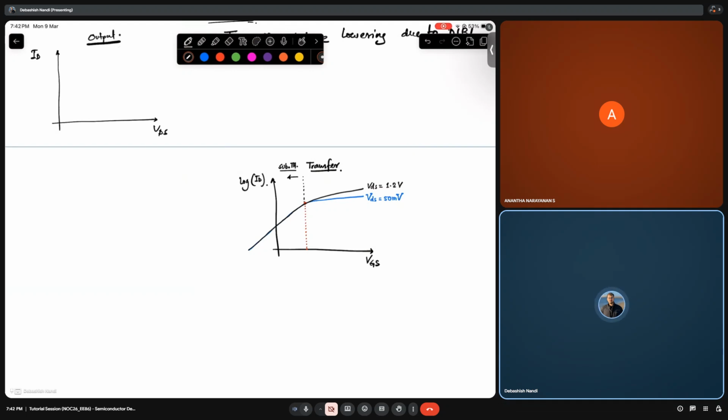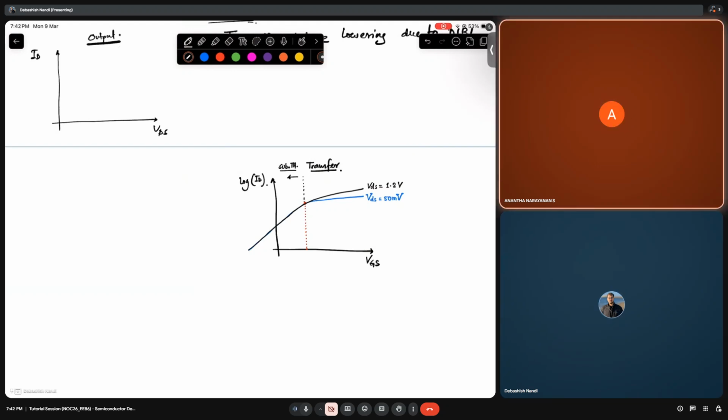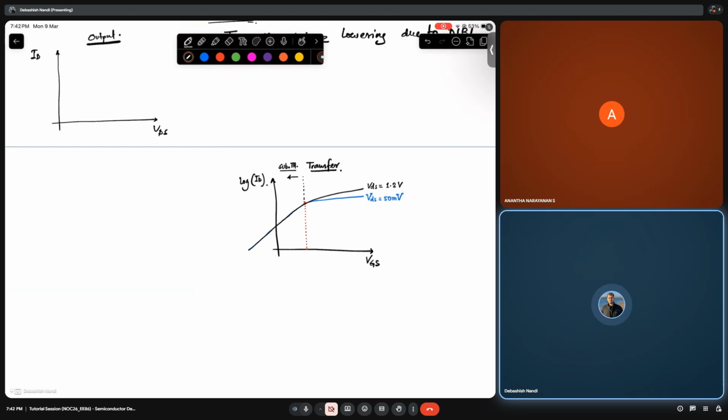My channel is not formed, right? So whatever drain voltage I may apply, my current will not flow. That will be the same current. In case of small VDS and high VDS, it will be the same current. Yes, sir.